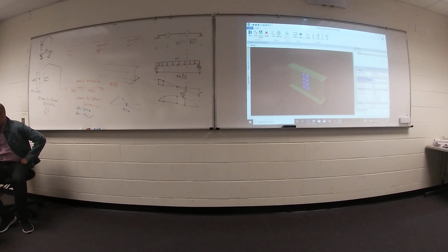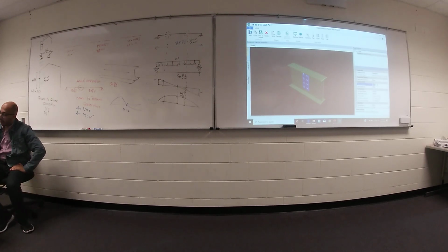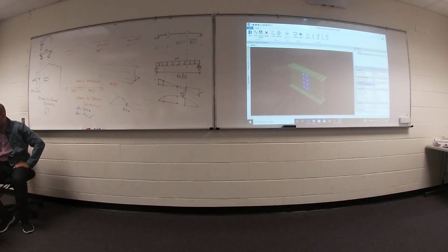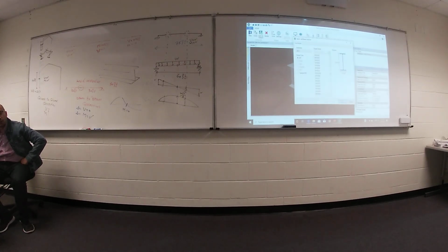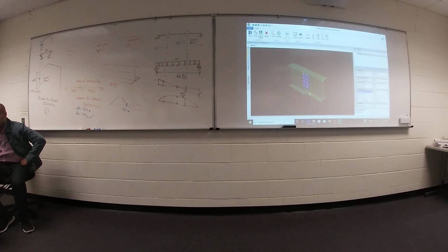Anyway, the second one, what is the value of your shear force? Go ahead to your shear force diagram and select what is the value. Maybe we can keep it 60. Then, what is the left beam cross section? Maybe your cross section is not W16 times 36. Go ahead and select the shape of your cross section. So maybe it's 18 times 50. Okay, so it becomes bigger. The second one also 18 times 50. So for the second beam, it chooses 18 times 50.